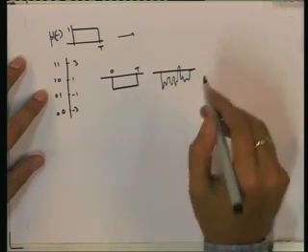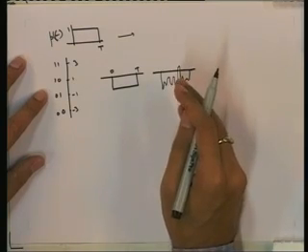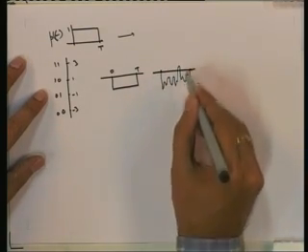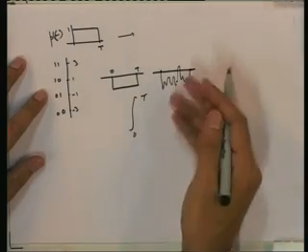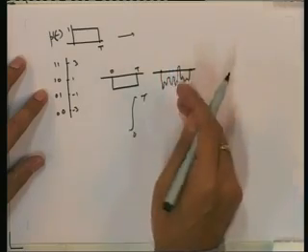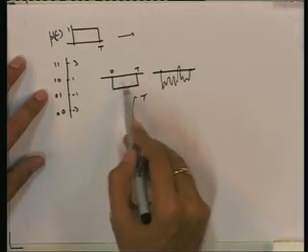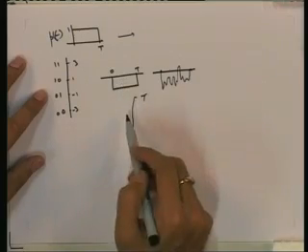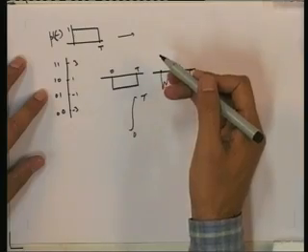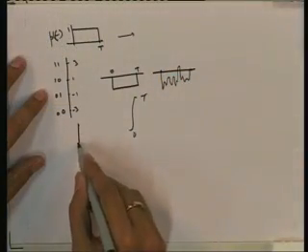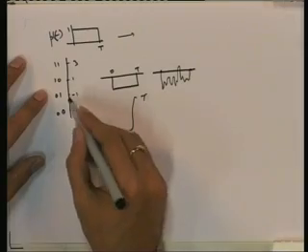some signal corrupted by noise. Now, one way to demodulate is to integrate this pulse in this interval. So, take 0 to T and integrate, and then compare that value with the values for, suppose, -1, which would give some value, -3, which would give some value, 1, and so on for 3. We will integrate and see to which of those values it is nearest, and that we will pick. If we integrate, it will be somewhere here probably. Then we will pick -1 because it is nearest to -1.